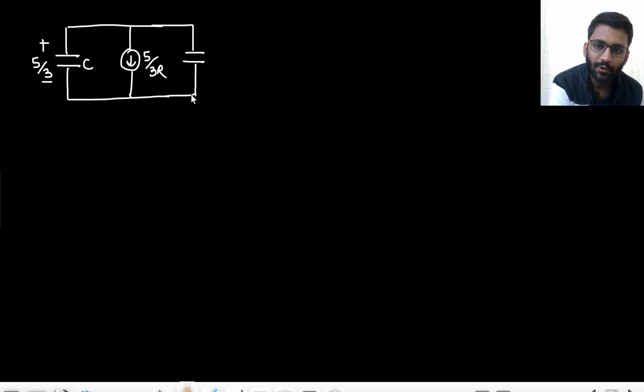So whenever there is a case of infinite current, something different will happen at t equals to 0 plus for sure. Because if there is infinite current, that means the capacitors are instantaneously charged. If the capacitors are instantaneously charged, that means there will be some current in the resistor as well that is connected in parallel. That current in the resistor has to flow through the capacitors. So the value of current will change. So at t equals to 0 you are having impulse current, but at t equals to 0 plus you will be having some finite current, and that value we are going to find now.